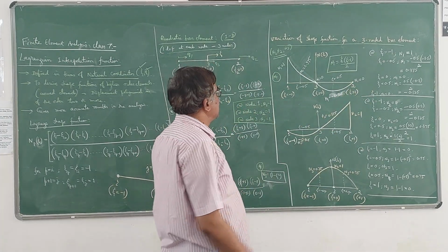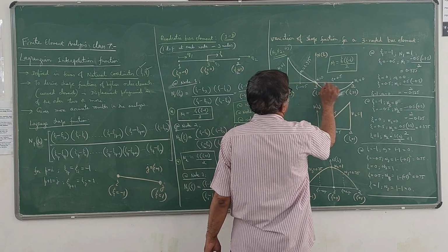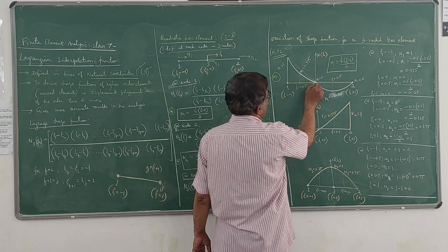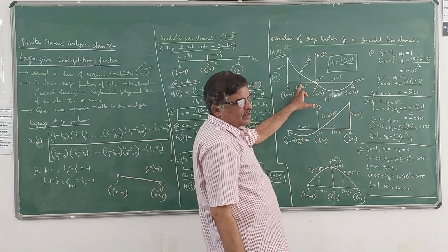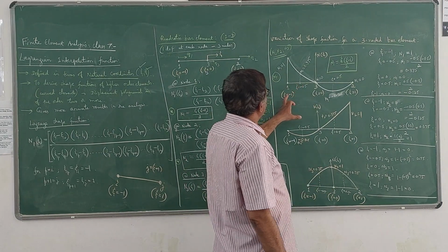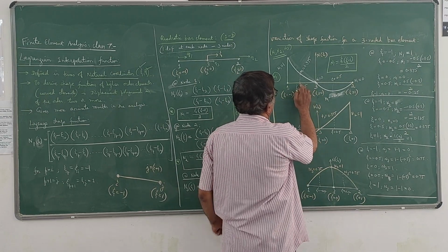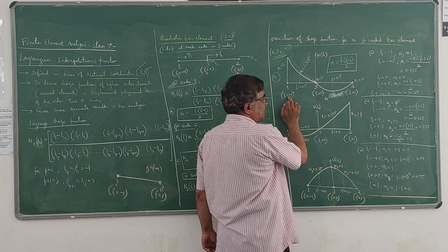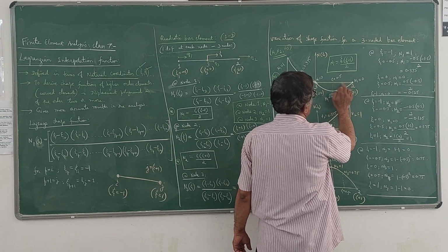So what I have done here is, I have taken these points, and I have taken the midpoint of them. If you take the midpoint of 1 and 3, it is not a node. Please note that this is not a node, I have just taken the midpoint. At the midpoint, the value of zeta will be the average of these two. So the midpoint will be minus 0.5 here, because this is 0 and this is -1. Here the midpoint will be zeta as plus 0.5.